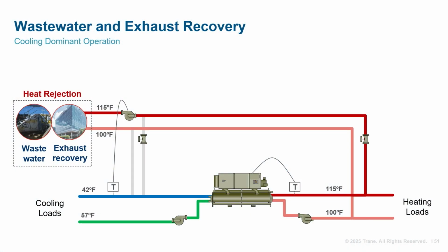This might be a little confusing because the heat rejection device is no longer hooked up to the chilled water loop. But as the heat rejection capacity is changed, the heat pump capacity will respond to maintain hot water temperature, resulting in chilled water temperature change. This is an indirect or cascaded type of control.